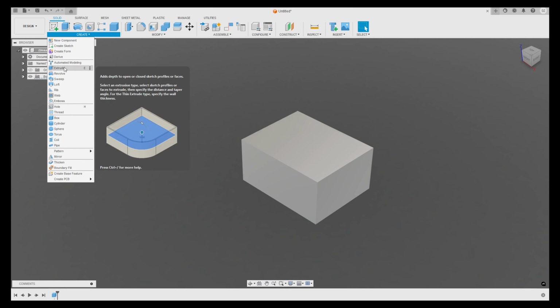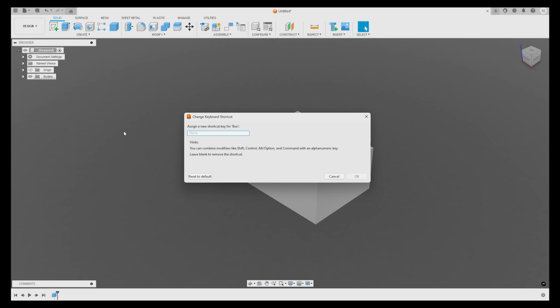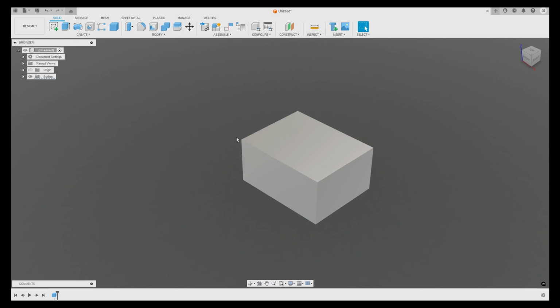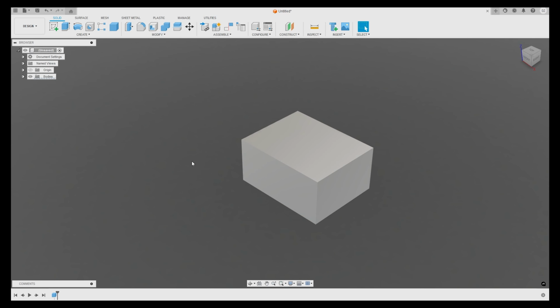In a similar way, we can set short keys like, when pressing the E key, the extrude function comes up. So let's select F3 key to access the Create Box function. So when I press F3, I can directly start to create a box. By pressing the Escape key, we quickly exit this mode. The disadvantage: you need a good memory when you define a lot of them. It's fast, yes, but using Shortcuts menu with the S key can be sometimes more interesting if you want lots of easy, accessible functions.